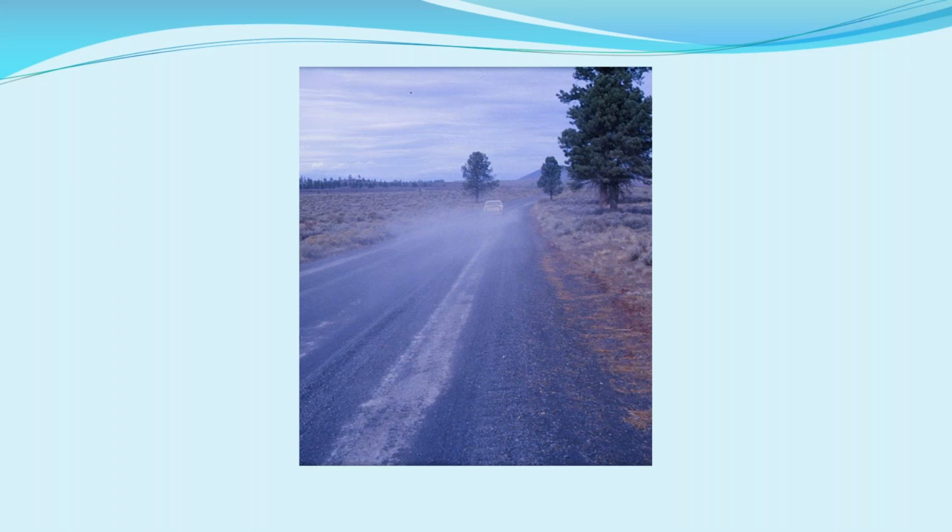If I came in here and I graded this roadway and broke that crust up, I would create more dust, and I'd lose more of that binder, and then I would have more of the loose material. So in some situations where you get a good crust on your roadway, don't tear it up, especially if you don't have moisture to put it back down, mix it back together, and lay it back down like it should be. Look, it's a gravel road. You're going to have some bumpiness to it, as long as it's not extreme and it's not unsafe. Sometimes you need to let those roads go.